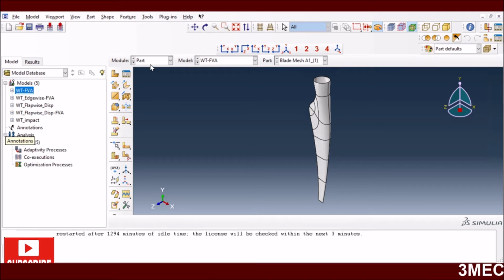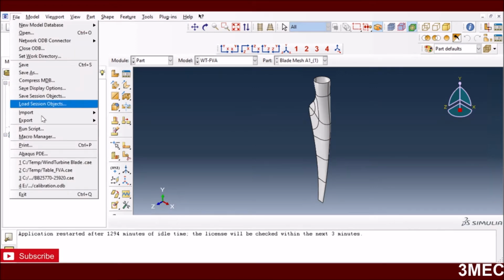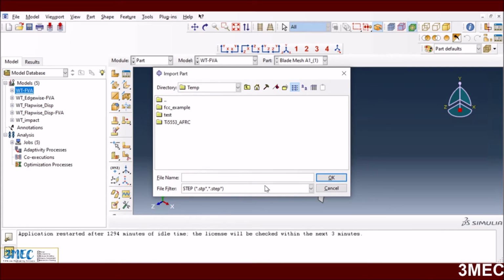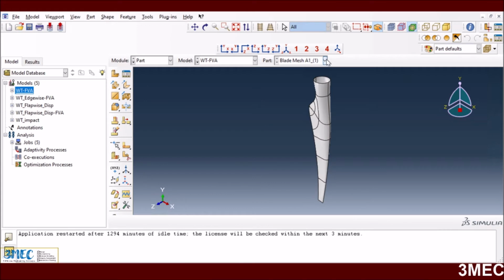Okay, so this is the model as you see on the screen. I took this model from GrabCAD. What I do is I just import the component as I normally do, and I can import many different formats. In this case I had an STP file, so I imported that, and once you import that you will have this kind of part. I use the default options. If you really want to do it, you can go and grab this one or any other 3D model from there.